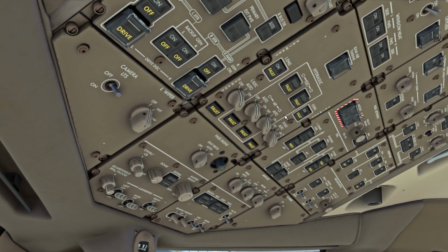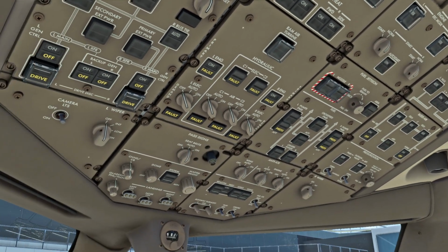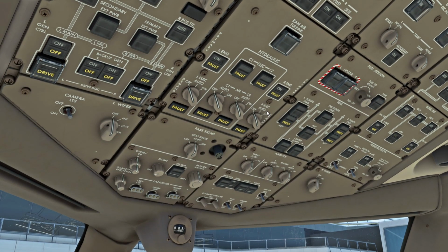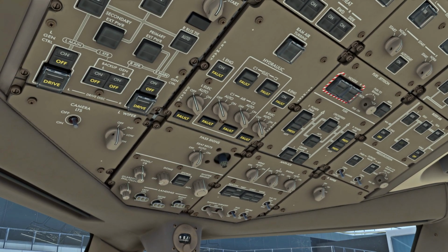On the 777 it's a little bit peculiar, the flow that we're going to go through now, so I'll just explain. We're going to turn the right electric demand pump on first, and the reason for that being there is a chance of hydraulic quantity moving from one system to the other if you do it another way around. And this goes through the parking brake system, through the braking system. It's a little bit complicated, but the default procedure is to turn the right electric demand pump on first, on auto. The fault light extinguishes, and then we can turn on the C1 and C2 electric primary pumps, and then we can turn on the rest of the hydraulic pumps safely.